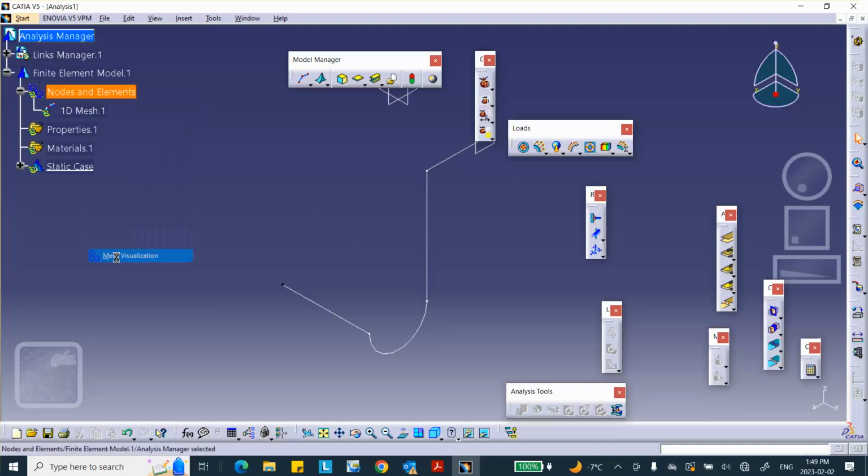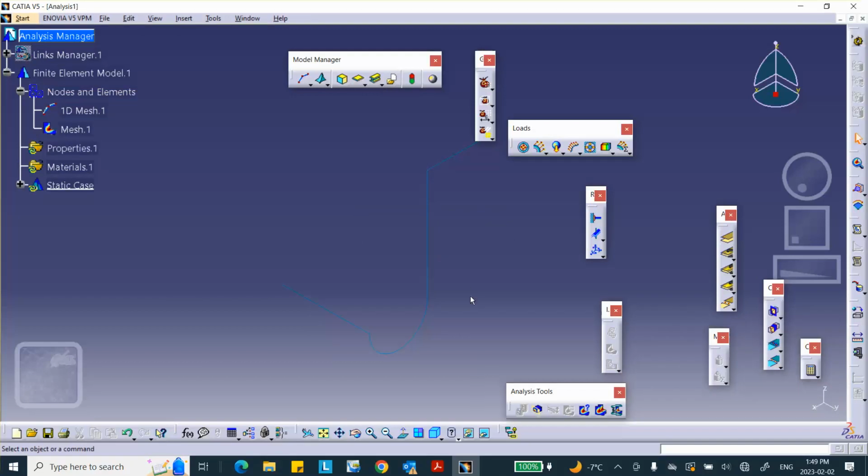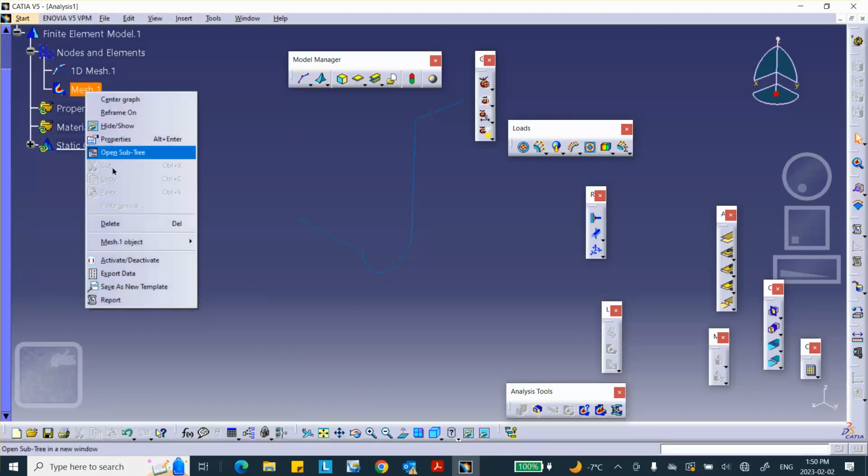If you look at the mesh visualization, you can see your mesh, nothing exotic here. Let's make sure that there are no duplicate nodes. See, this corner node is node 4 when you go from this side, and it is also node 4 when you go from the other side. If you had not joined this thing, there would have been duplicate nodes here. There are ways to fix this, there are ways to handle that, but I don't want to do it. We haven't talked about it, so deactivate.